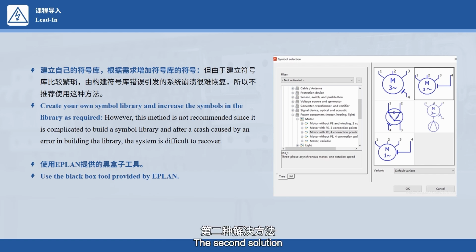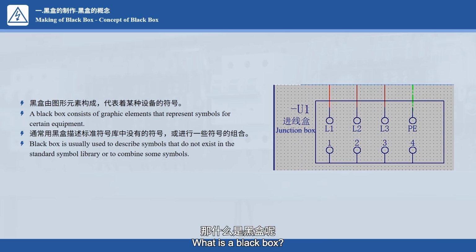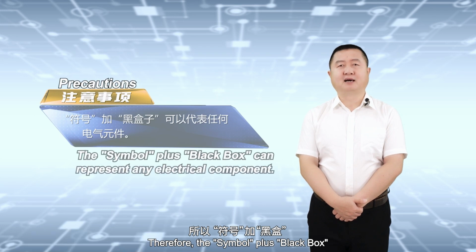The second solution is to use the black box tool provided by E-Plan. What is a black box? A black box consists of graphic elements that represent symbols for certain equipment. Black box is usually used to describe symbols that do not exist in the standard symbol library or to combine some symbols. The concept of black box was introduced by E-Plan to deal with insufficient symbols in the symbol library. Therefore, the symbol plus black box can represent any electrical component.